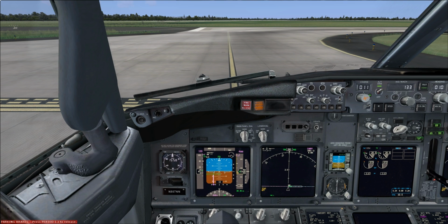Now if you're well into the takeoff roll, the rudder is picking up enough airflow over it, it's effective, everything is nice, and you get the strong crosswind from a microburst from your left or your right. Depending on how strong it is, you might be able to fly out of it. You might be able to keep the aircraft on the runway, maybe not on the center line, but long enough to get off the ground.